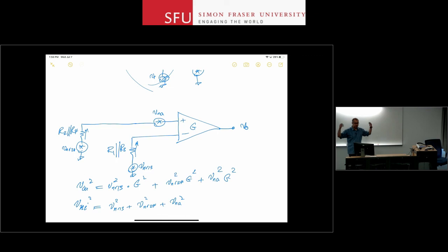my system in theory has, let's say it's a photodiode, right? It has unlimited bandwidth practically for whatever amplifier that I'm putting in front of it. But I don't need all that bandwidth. So first thing I do is that I go and put a low-pass filter in front of it. The second problem I have right away is that with the low-pass filter, I have the 1 over F noise. So if I put a low-pass filter in front of this circuit, the 1 over F noise will kill me if I'm only interested in the lower portion of the frequency.